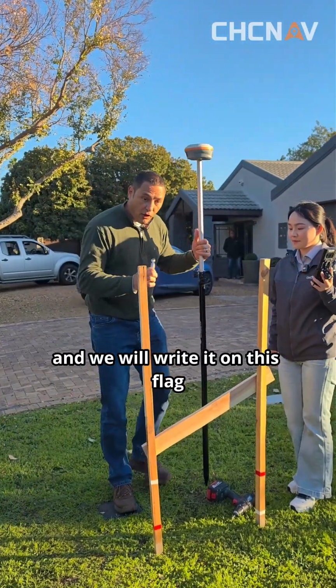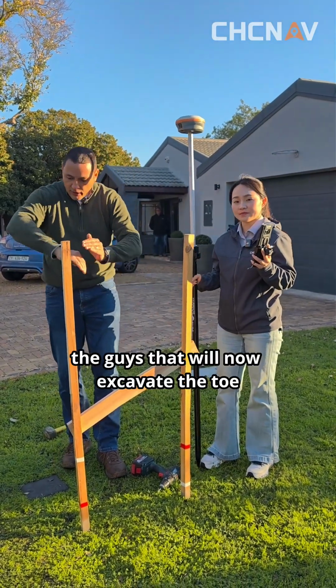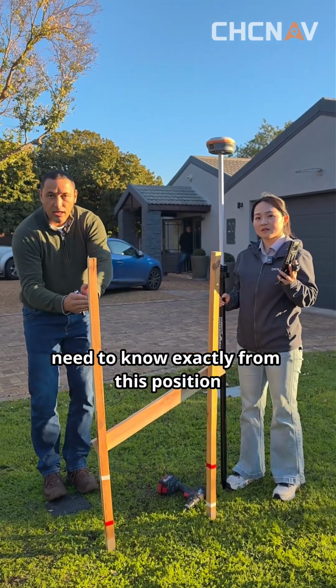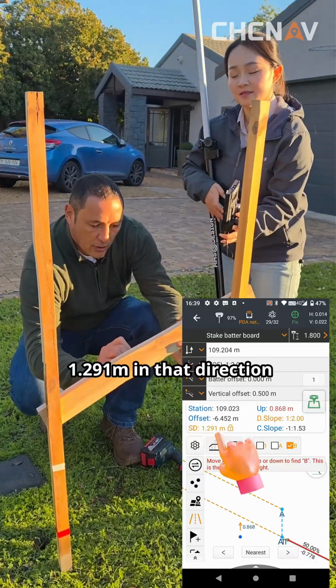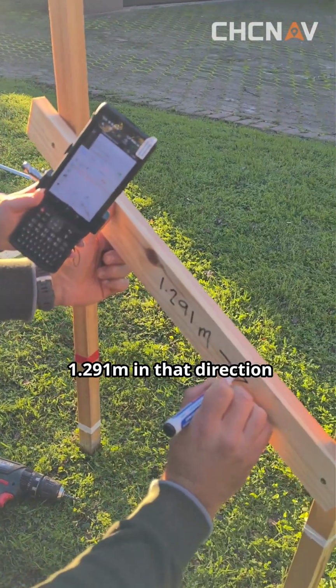And we will write it on this plan because the guys that will now excavate the toe need to know exactly from this position how far they have to excavate at that slope to get to the right position. So we'll write here 1.291 meters in that direction.